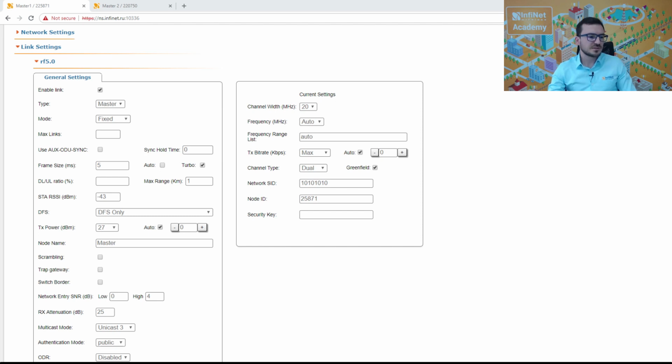It might happen that the reflected signals from the surface of the sea could affect the quality of the link. Next question, can the base station or CPE interfere with 5 gigahertz homebox internet? Yes, of course. If they use the same frequency, they can interfere with each other. So if they are closer than a few meters, I don't know, closer than 5-10 meters, you have to be careful, because by chance, if they use the exact same channel as I showed during the webinar, the interference will be very high, and there will be problems with both the homebox and the Infinet devices.